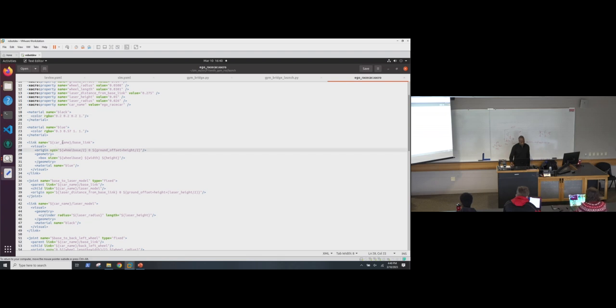But you're describing the base link as the base. I'm going to bring up Gazebo to see the actual frames for that. But these are the frames. This is where the LiDAR is located. It's the XYZ position from the origin. So if you move your LiDAR to a different position, you might want to just figure out the new height and stuff, and then put it in here.